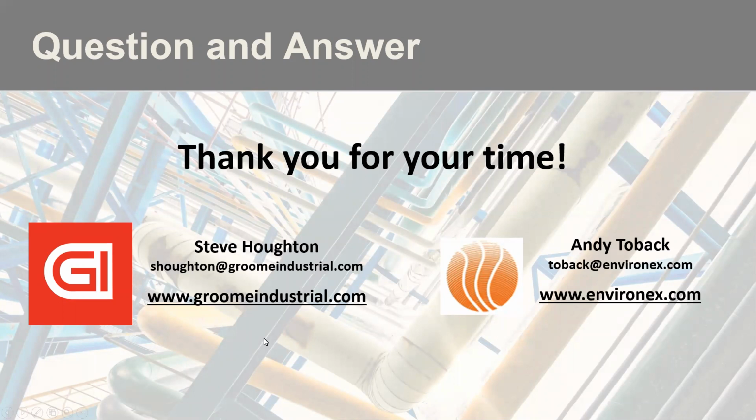So to answer the question of what do you do when you got two operating modes, I've done it for base load and turn down. I've done it for SCR catalyst systems where the temperature coming out was hot enough, or was cold enough rather, where you could do a tune with the tempering air fans on and off to come up with an optimal tune that way. And this wet compression fogging is no different. So what we would do is we would traverse the duct in one of those operating modes and then do the same thing in the other operating mode, and then come up with whatever is the optimal for both.